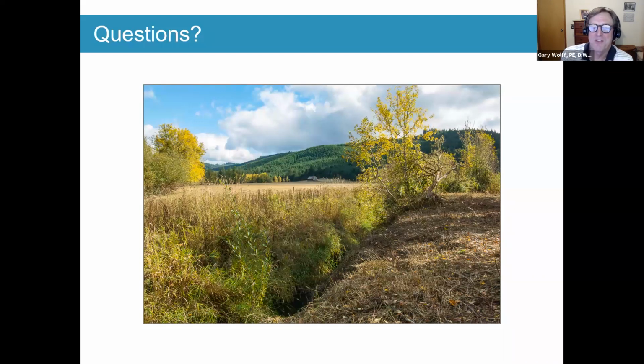We did, as part of this project, look at the hydraulic results very carefully, comparing existing to proposed. And that's why, again, understanding the existing characteristics of the stream is very important. There really are no obvious sedimentation issues with this stream. It's basically what we would call a threshold stream. There is some fine material in there, but it's not a dominant bed load transport stream. So honestly, sedimentation is not going to be an issue with these bridges, and we've made the waterways similar, maybe a slight improvement from existing conditions where there are no sedimentation issues.